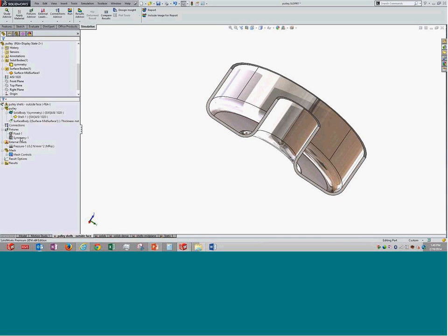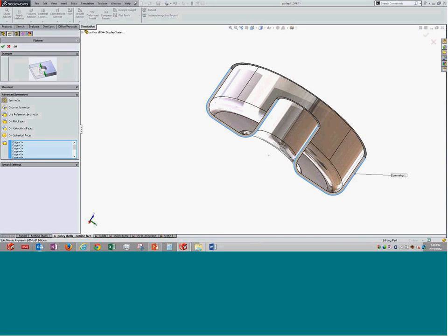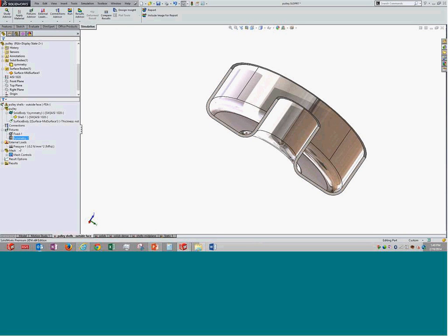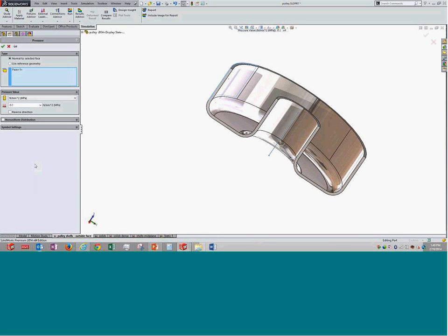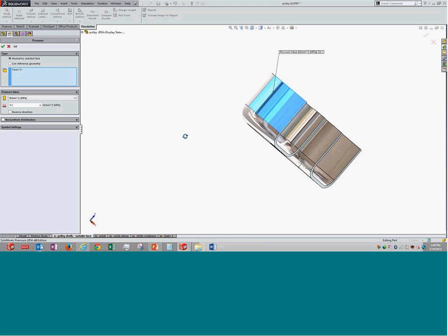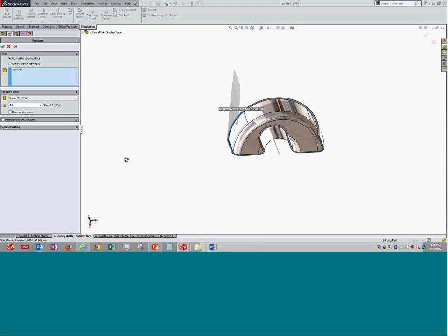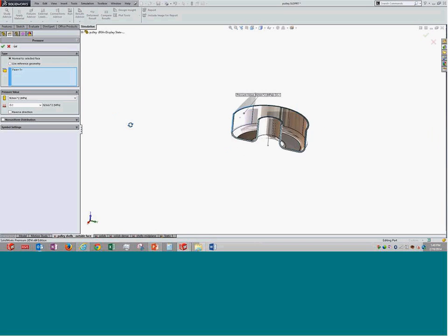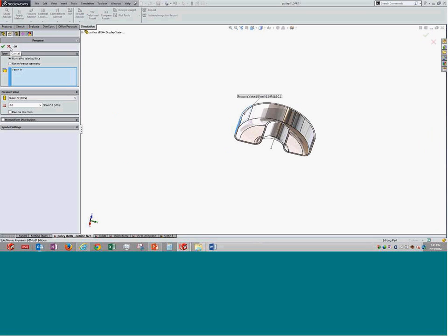In terms of surfaces and applying pressure, ensure that we are applying the pressure on the surface that is being meshed or used for shell elements. Sometimes we end up making that mistake because the solid entities are also present around. We might end up doing that mistake. Make sure we are selecting the right surface. Finally, let me solve it.